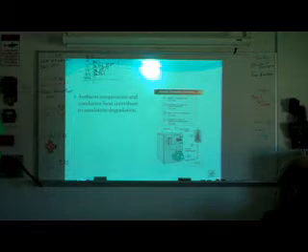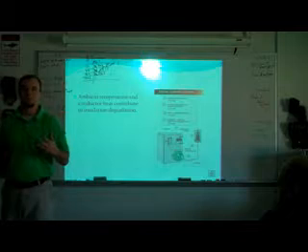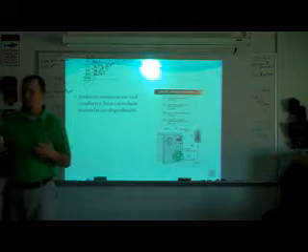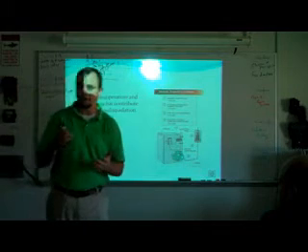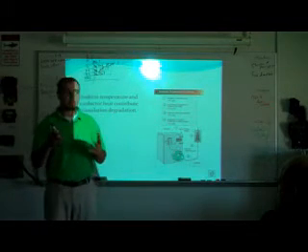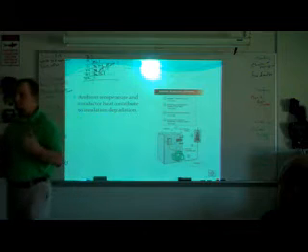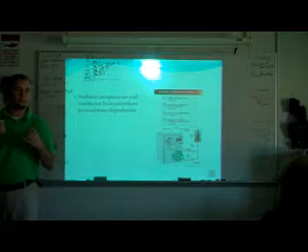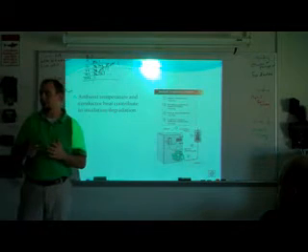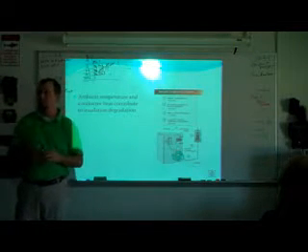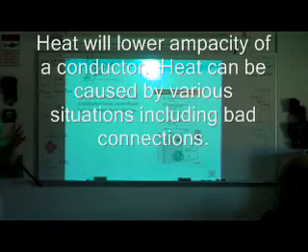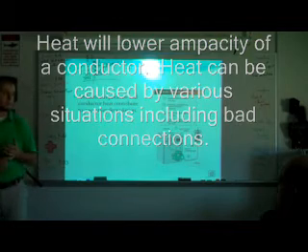I know at Camoplast, when we were working on their injection mold, it is very, very hot, because they have to keep their molds at about 350 degrees Celsius. So you have that much heat from trying to keep those molds hot, and you've got wires running next to them. That's when it really pays off to understand what type of conductor you're going to need. You guys need to remember that heat will lower your ampacity. That's the main thing. Heat will lower your ampacity.